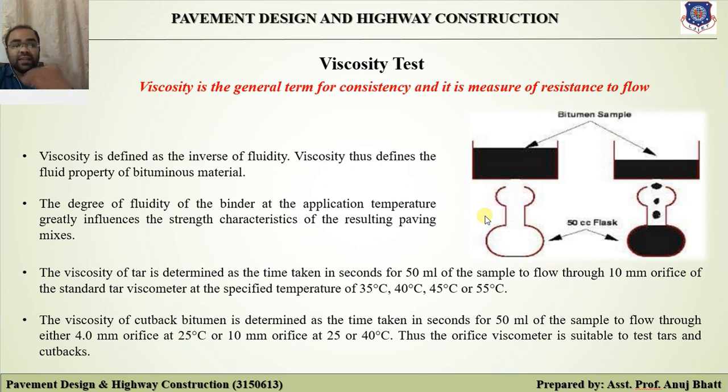At a certain temperature it starts melting. So at a temperature this bitumen melts and falls into the flask. As this bituminous material melts and falls down into the flask, the time required for 50 ml of material to fall down is measured, and from that we consider the viscosity, or the viscous property, of that bitumen.